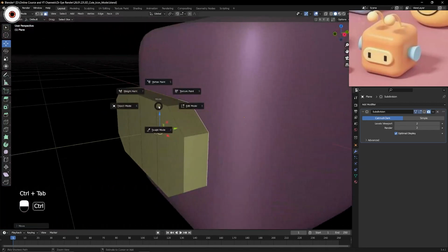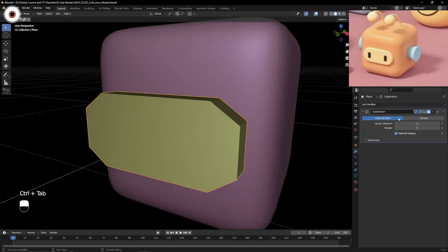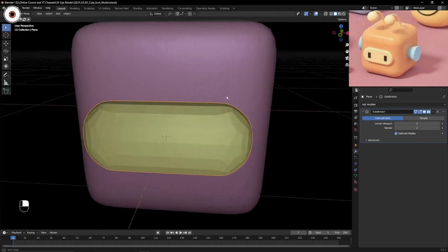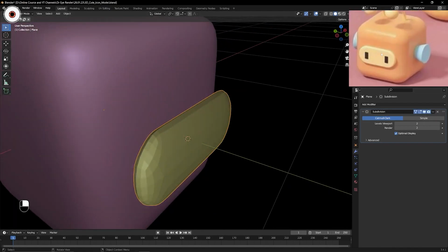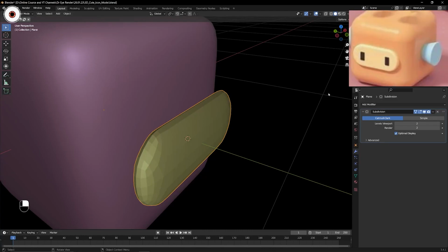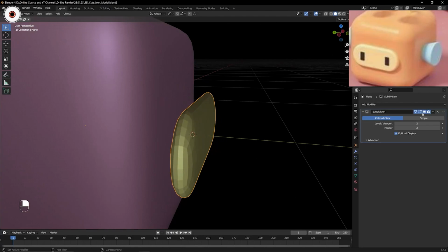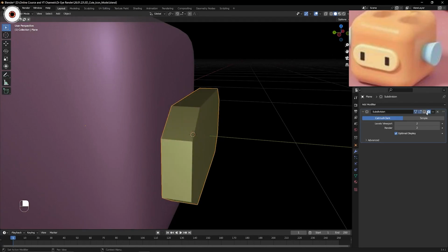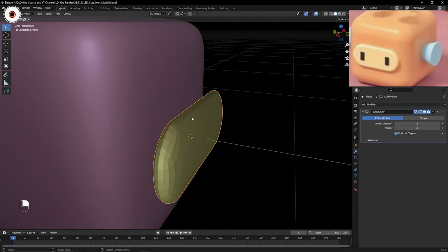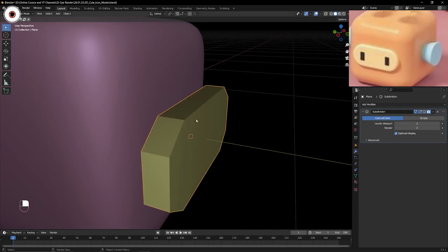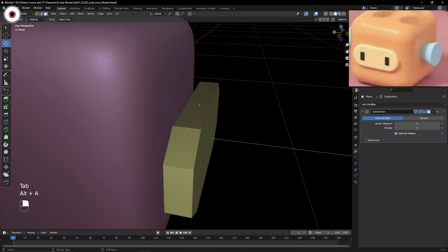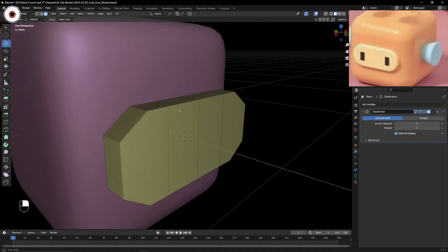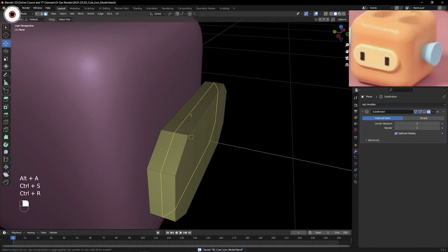Alright, so we have a shape. Now we can turn on the subdivision modifier, but the issue is here we can see there is a hard edge, but we don't have the hard edge. We are having it, but after adding a subdivision modifier, it's not working in the right way. So for that we need to add some extra topology over here, right? So Control R, and you can press the addition symbol on your numpad, by which the loop will get duplicated.